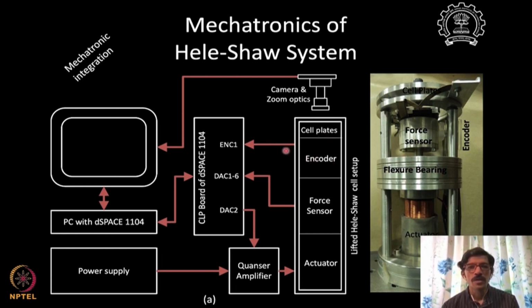Now how do you take encoder input? We are using this controller as a dSPACE control system here. You can also use other embedded systems, like a TIVA microcontroller, and that's fine, no problem. What we are using here is an encoder to sense the position of this system. Then the force sensor input is taken by an analog to digital converter, so this should be the ADC here. Analog to digital conversion is happening here, and that data is in your microcontroller.